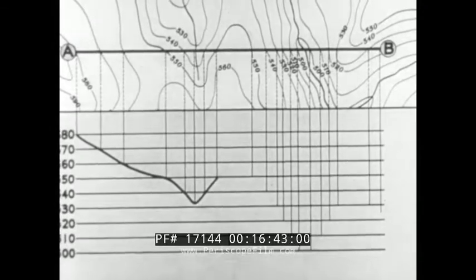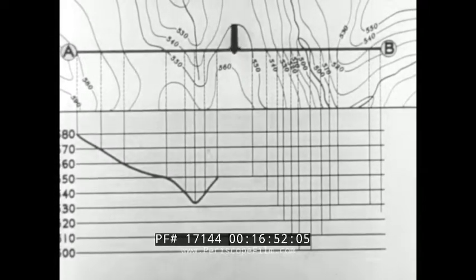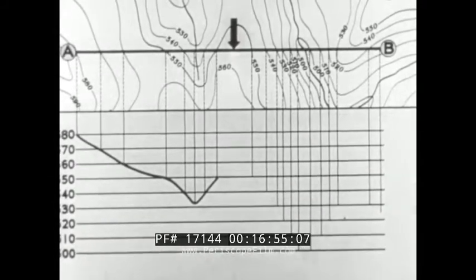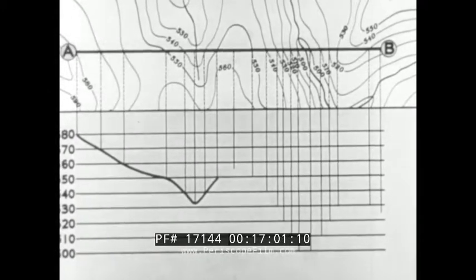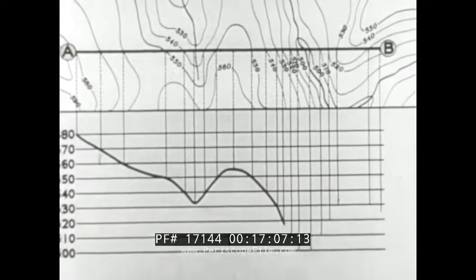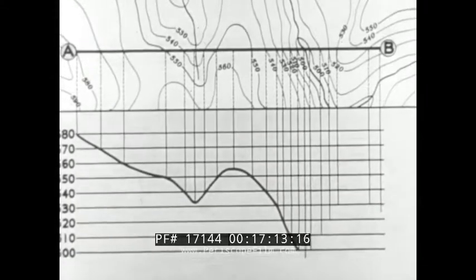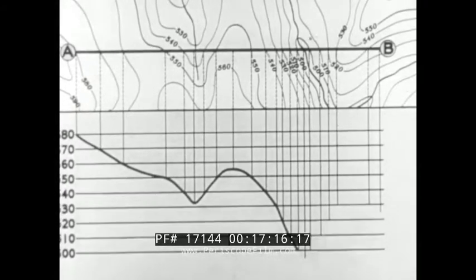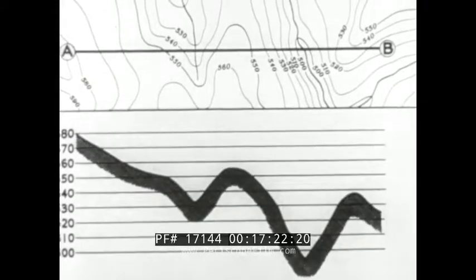At this point, between two elevations of 550, the line AB reaches an elevation of approximately 556 feet. In other words, a crest or hilltop occurs here. A corresponding crest should appear on the profile. By interpolation between 550 and 560, indicate the high point of the crest and continue the profile. Here, another depression or valley occurs as the line AB crosses the stream. It is so indicated on the profile. The result is a fairly accurate picture of the surface of the ground along the line AB.